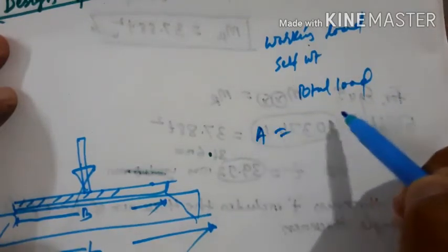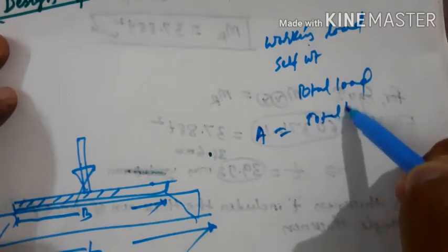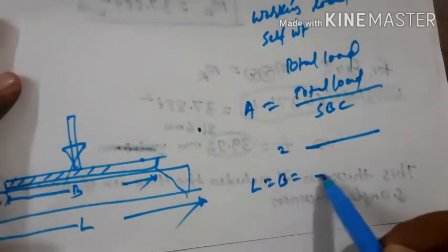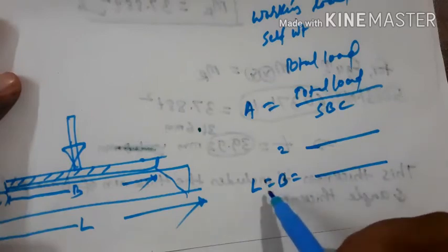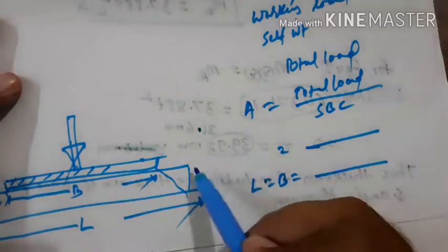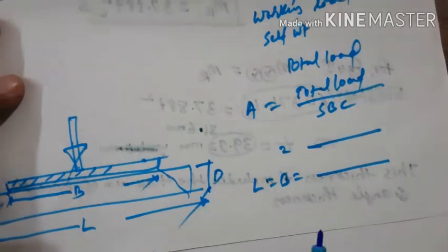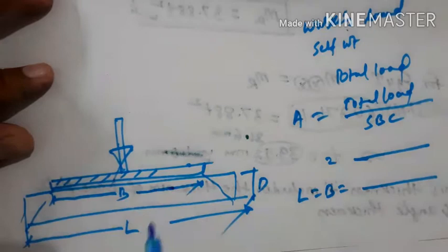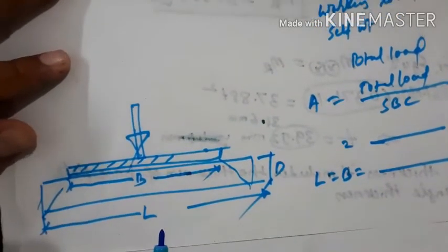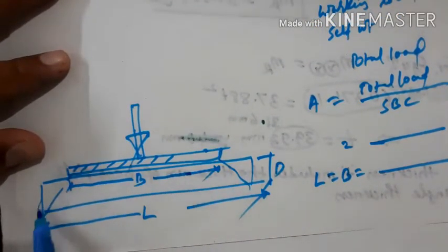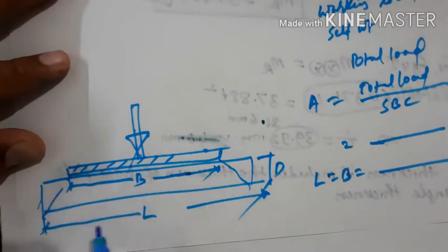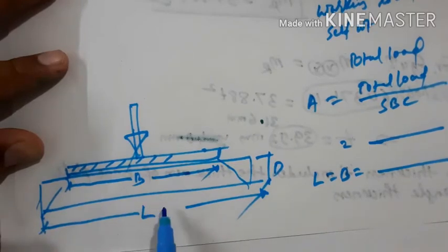The area required is total load divided by SBC of soil, then you'll get an area. Assuming a square base, you get length equal to breadth, then you calculate the depth of pedestal required. So just follow the steps given in the earlier problem, where I also solved this type of concrete pedestal, how to design the concrete pedestal and calculate its dimensions. Please go through the previous problem, you will understand.